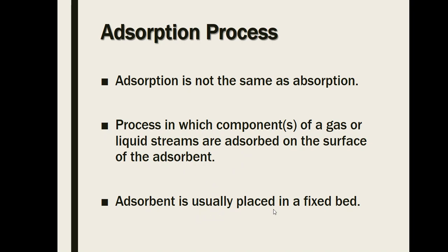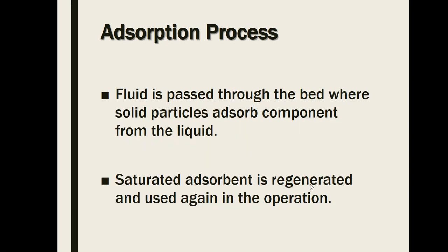Adsorbent is usually placed on a fixed bed. It could also be in a fluidized bed, but often the solids that need to adhere the component from a particular fluid are placed in a fixed bed. Now the fluid is passed through the bed where solid particles adsorb the component from the fluid, be it liquid or gas.